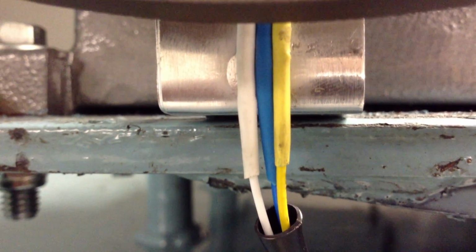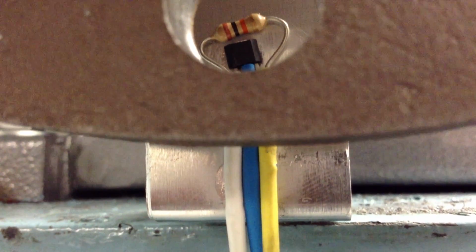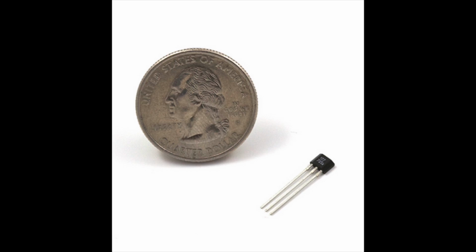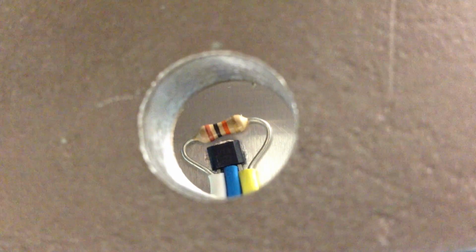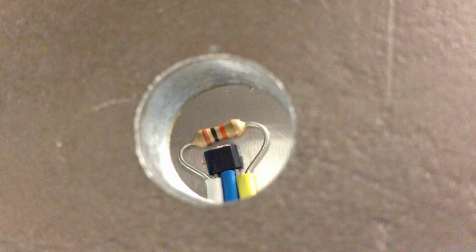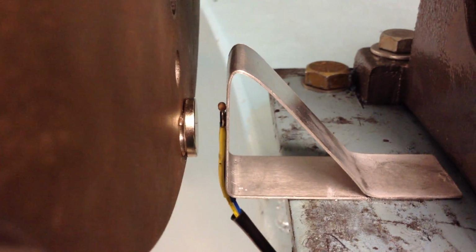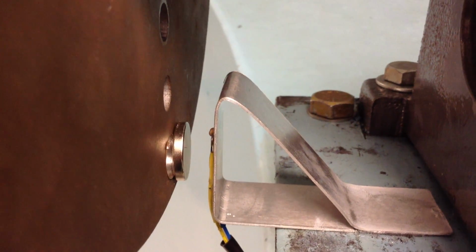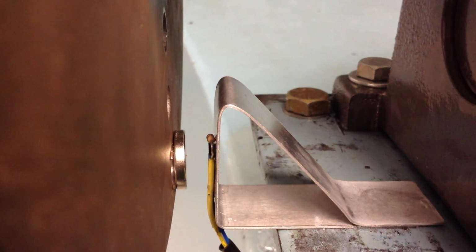There are 3 types of Hall effect sensors: linear, latching, and non-latching. The sensor used for this system is a US 1881 latching Hall effect sensor. A Hall effect sensor is a transducer that provides an output voltage when it senses a magnetic field. A latching Hall effect sensor means that once the trigger is engaged, it remains engaged and will not unlatch until a magnetic force of opposite polarity is sensed.